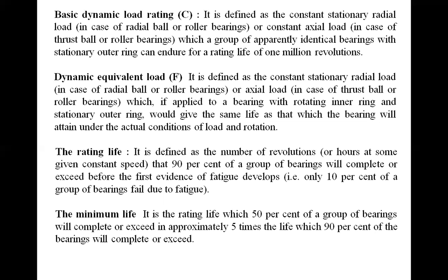Dynamic equivalent load is again a combined load: when the radial and axial loads are combinedly taken by the bearing, and a rated life of 1 million revolutions is achieved under the actual load condition, then that is called the dynamic equivalent load. Dynamic equivalent load takes care of radial as well as axial load combined.